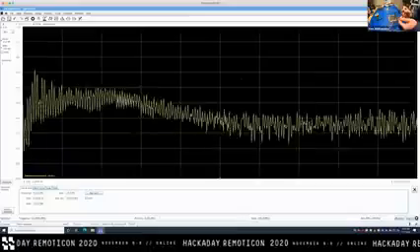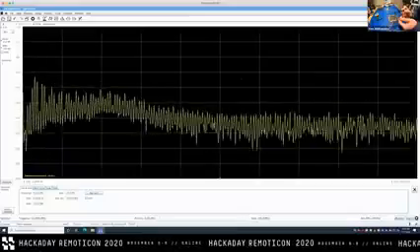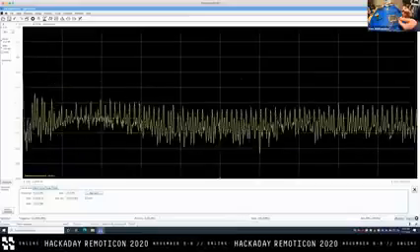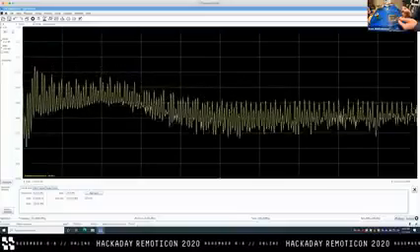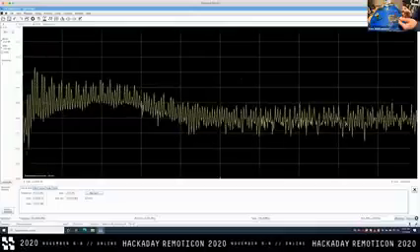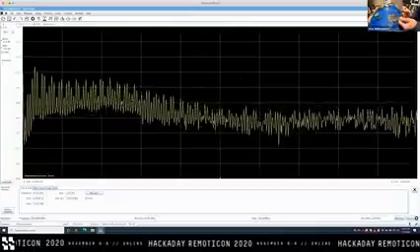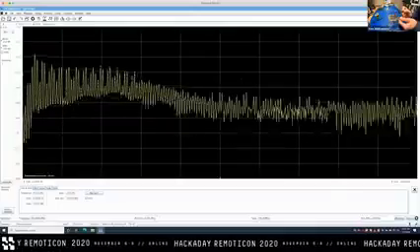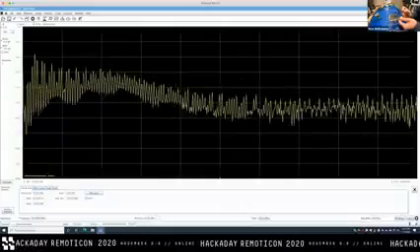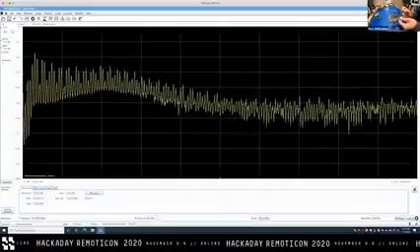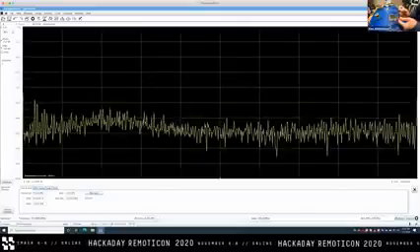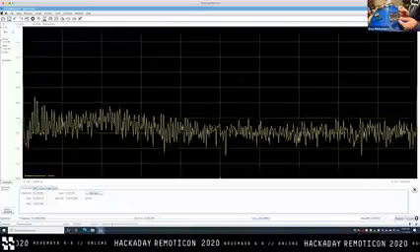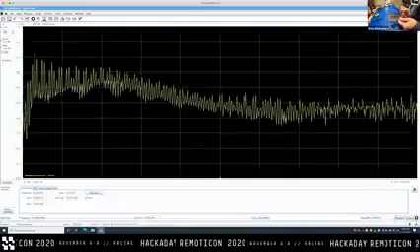And this is one of the key areas where the difference between near field and far field is important. The fact that we're detecting all of this noise doesn't necessarily imply that this noise exists in the far field electric field. So this might be cause for concern, but it's not actually, because we know that it passed the test report. Actually, for this device, we don't, but I assume it did. I mean, it probably didn't. I don't know. Anyway, we don't necessarily have to worry about it.